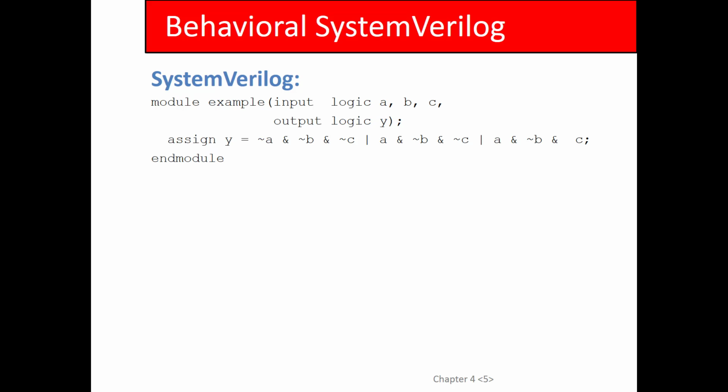You can use Y on the right-hand side in as many lines of code as you want. That represents a fan out. So this Y can be fanned out, connected to a bunch of inputs, but it can only be set once. So even if it's in a different module, it's still not allowed. No, because that Y is the same signal connected throughout the hierarchy. Like I said, it may be called something different, and I'll show you examples of that in a minute. I'll get to that soon.